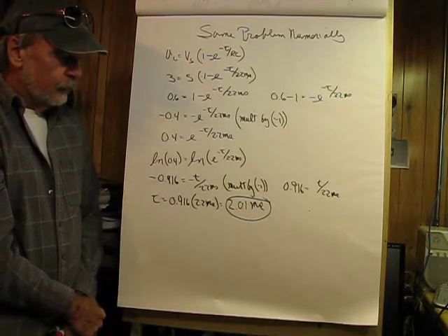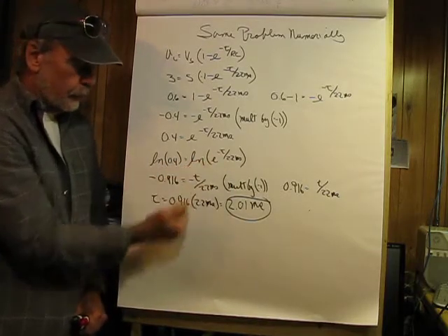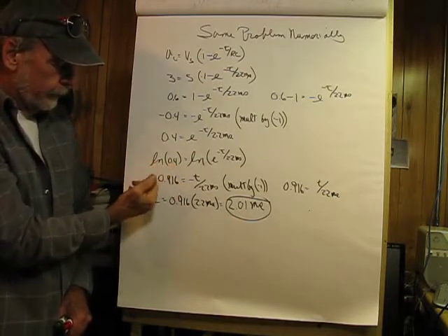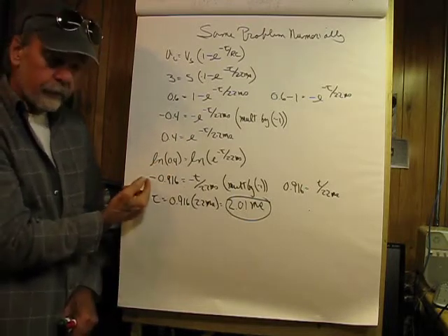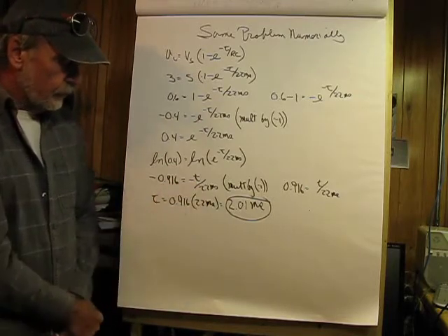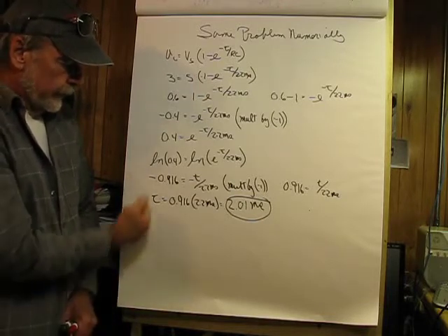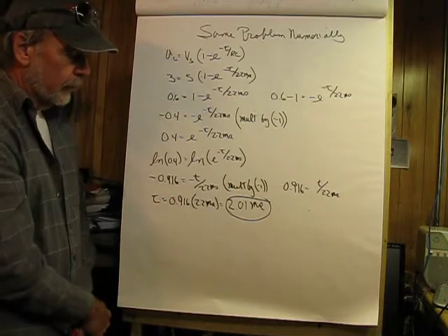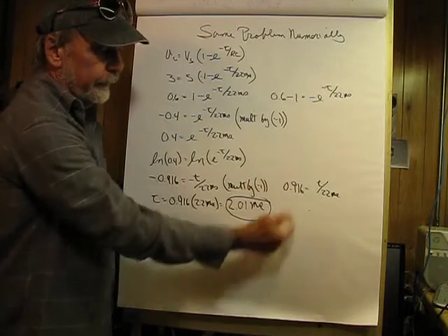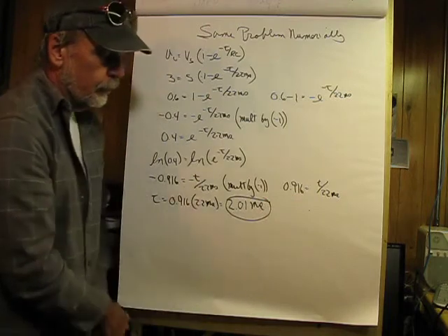And then, since I want to isolate t, I'm going to take the natural log of both sides, written out to show the operation here, and that will give the natural log of 0.4 is negative 0.916 equals negative t over our time constant, 2.2 milliseconds. And getting rid of the negatives again, multiplying by negative 1, we end up with a positive 0.916 equals t over 2.2 milliseconds, our time constant.